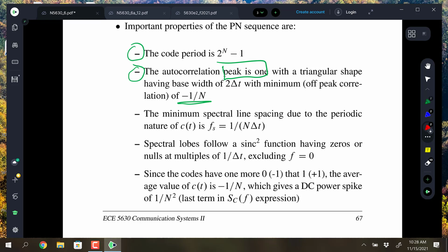And when I have students do labs in the COM1 class, they look at the M sequence. An M sequence, if it's got a shift register of n bits long, there always is going to be one pattern of n ones. There'll be a pattern of n minus 1 ones all the way down. So you're going to see occurrences of these subpatterns in an M sequence. But one of the things is you're always going to see a pattern of all ones, n ones. If you were to see a pattern of n zeros, the shift register would stop, because it can't function then. So you've got to have it filled up with some ones.